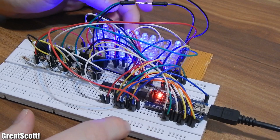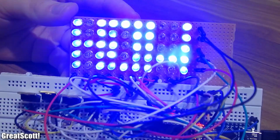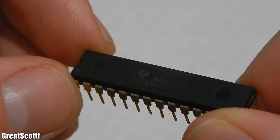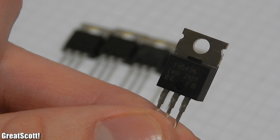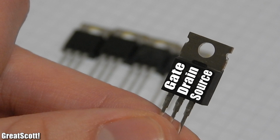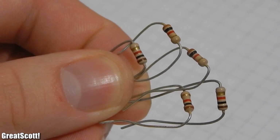So I'm going to show you how to control many LEDs with only a few I/Os. And I will only use an Arduino Nano, one TLC5940 LED driver, 5 P-channel MOSFETs, the F9540N, one 2K resistor and 5 1K resistors.